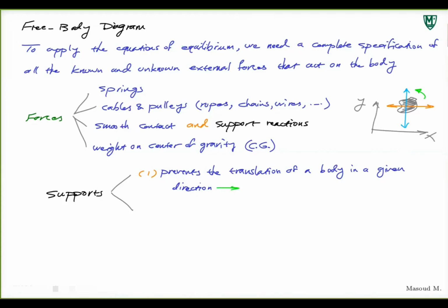So when we remove that, what happens? We have to take that support into account as a reaction on a rigid body. What that support does is exert a force in the opposite direction. If it's preventing this from going downward, and I remove it, I have to exert a force in the opposite direction of the motion that it is preventing.